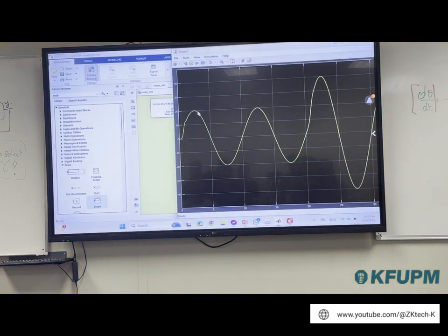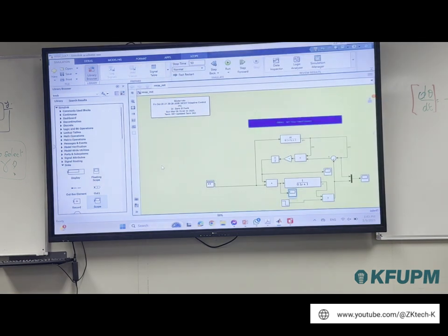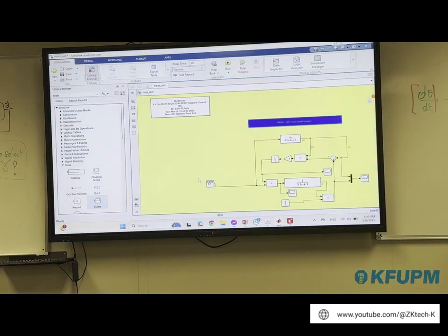Right? It goes to 20 because of the difference between them, and then after that, it oscillates. Actually, it depends on the system here. If you have DC, remember, UC is 2, but the gain of the system, K naught, is equal to 10. So we are expected to reach 20. And this is why your control reaches 20. And then after that, we reduced by half, so it has to reach 40 again. Everybody is okay with this?